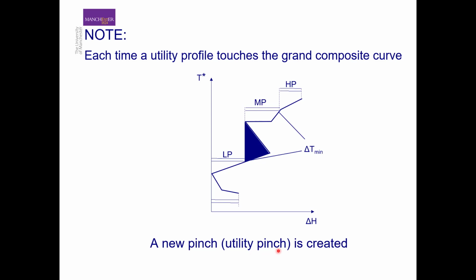Now, these utility pinches are going to be very important, and we will see in the next slide how we can actually use them in design. But this is just to say that where a utility touches the grand composite curve is what we call a utility pinch.